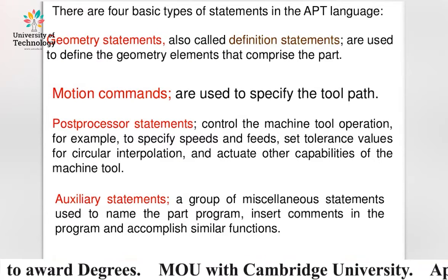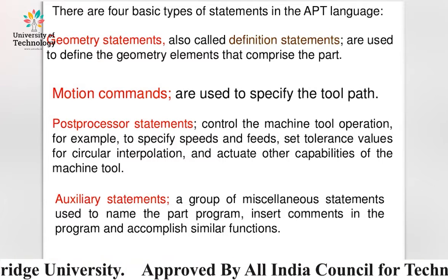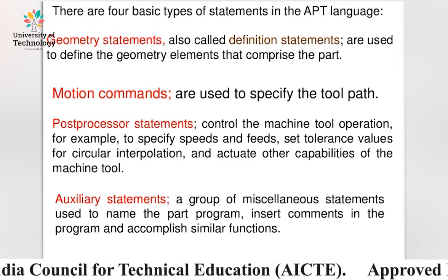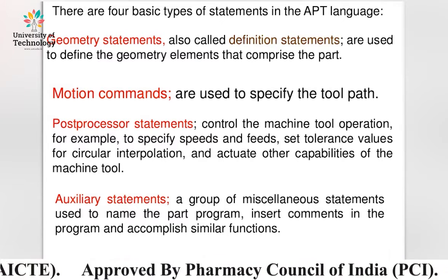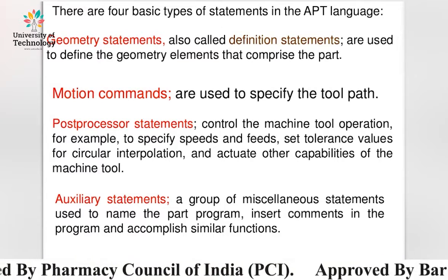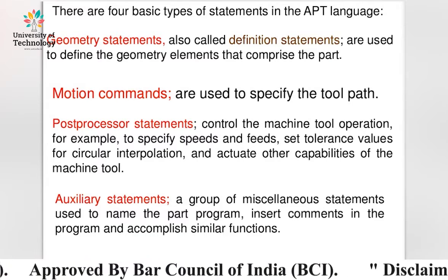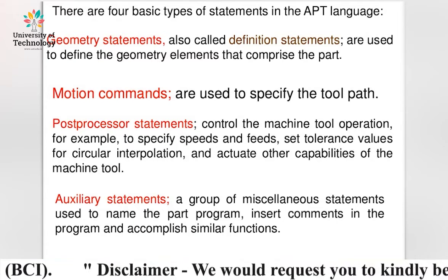And post-processor statements control the machine tool operation, for example, to specify speeds and feeds, set tolerance values for circular interpolation, and actuate other capabilities of the machine tool.